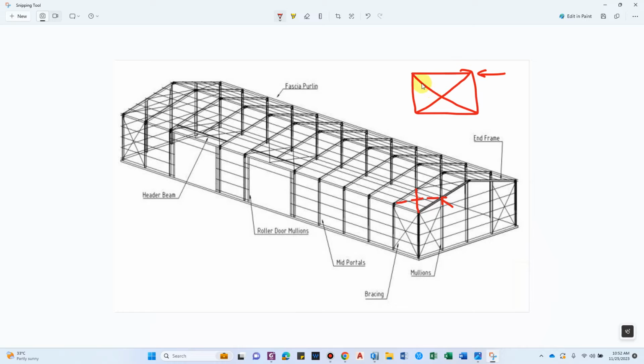See, these bracings are generally provided as an angle section or a simple rod. Let us consider a rod, and the rod being simply capable of taking tension only. So you can simply consider a reinforcement type rod, 16 mm rod or 20 mm rod, that is not capable of taking compression, only tension. So this goes into this strut, right?